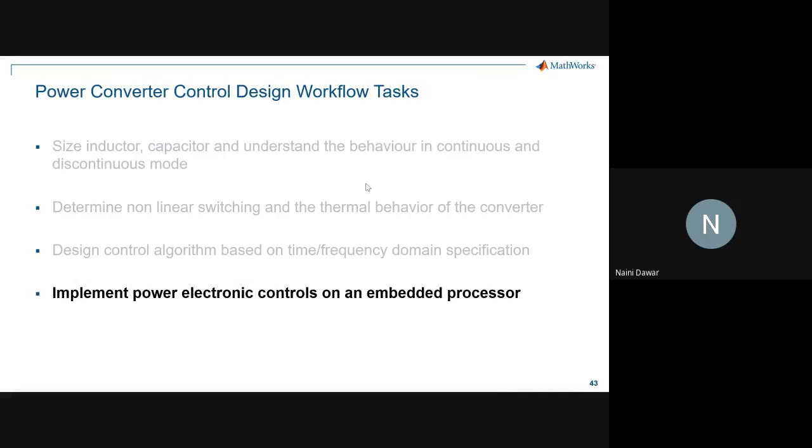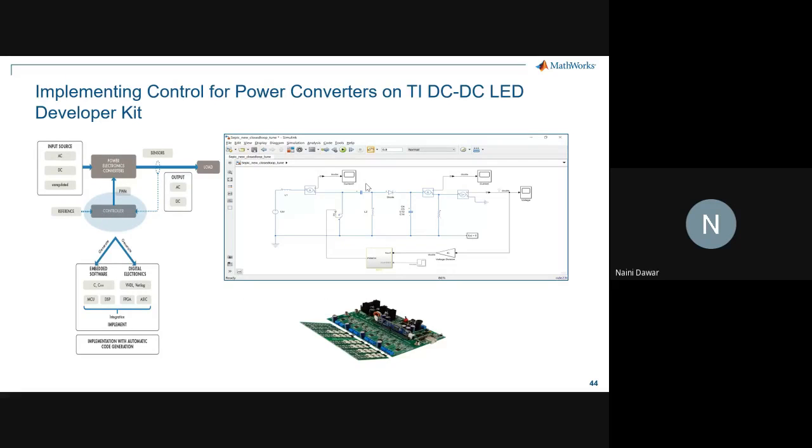Right. So the fourth part is also very important from the code generation perspective. Along with the MATLAB Simulink tools, there is something called the hardware support packages. As I mentioned, MATLAB Simulink has the capability to automatically generate the code and deploy it to the hardware. In some cases, like Texas Instruments, there is a direct integration available. There are direct device driver blocks available, and you can simply download them. You don't need to purchase them separately. If you're using a licensed version of MATLAB, you will have access to the add-on support packages as well.